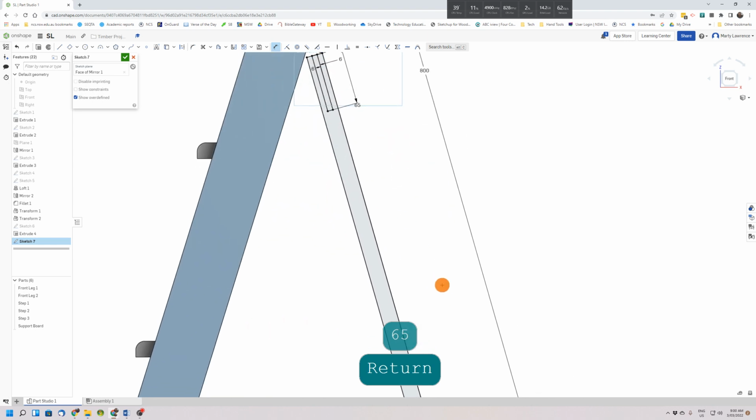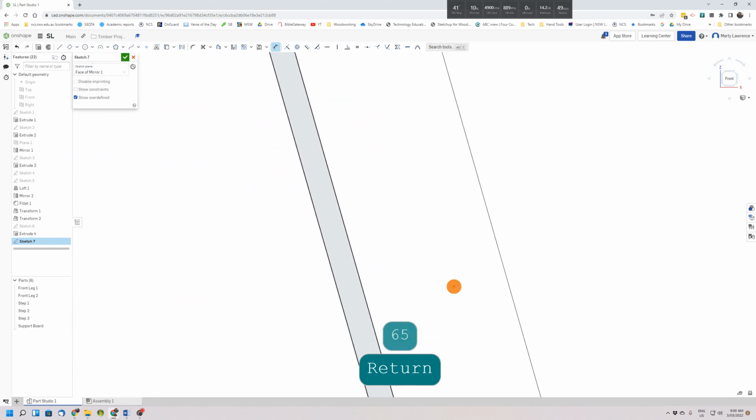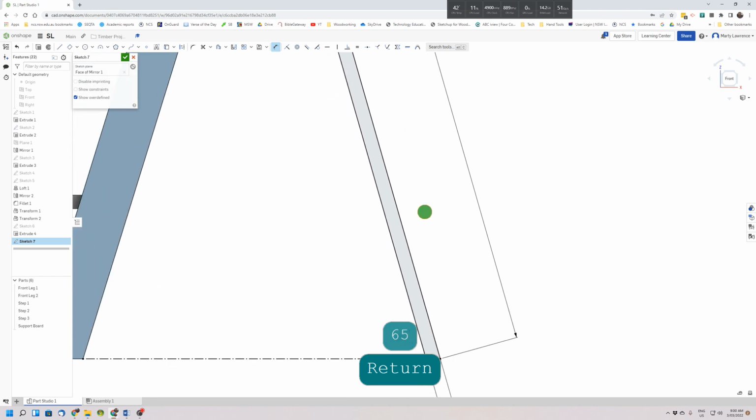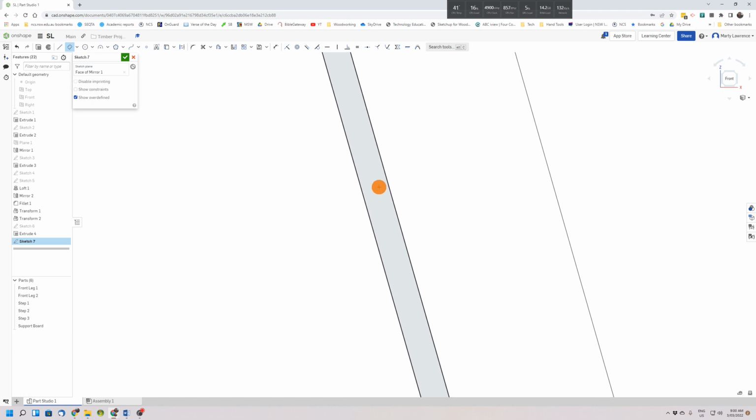Okay, now we're going to move down towards the bottom of our leg there, and we're going to again choose the aligned rectangle tool, and somewhere inside this space, make sure you're not selecting against edges but just between the two edges, click once. We want to get the parallel line icon so it's parallel to that existing edge, click, and then our last click inside that space there, and we're going to set our size with the dimension tool.